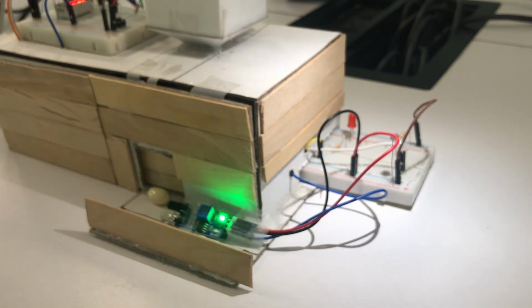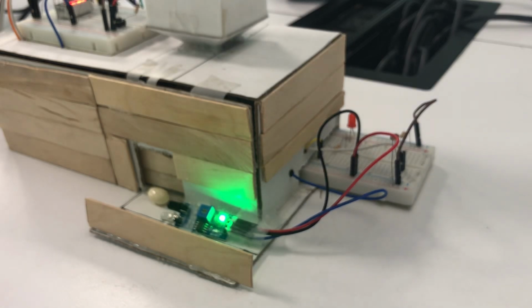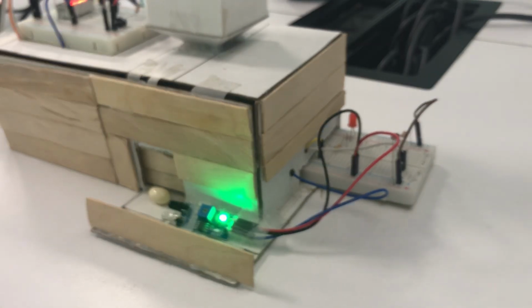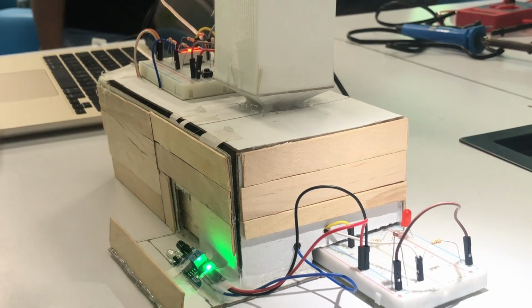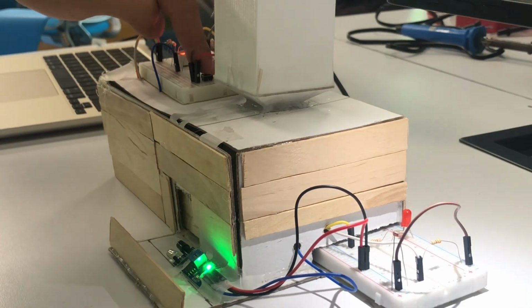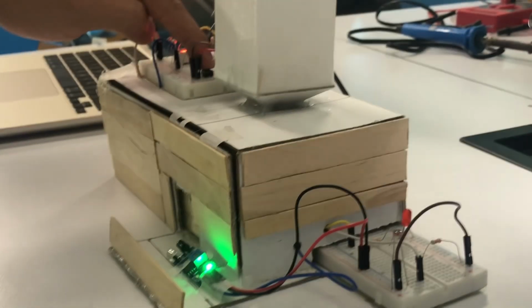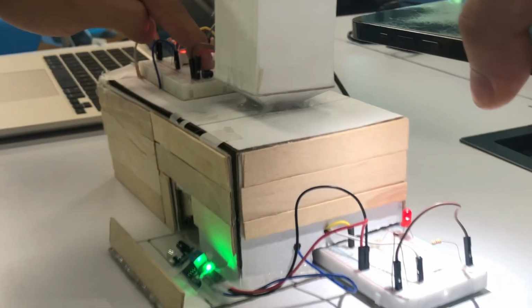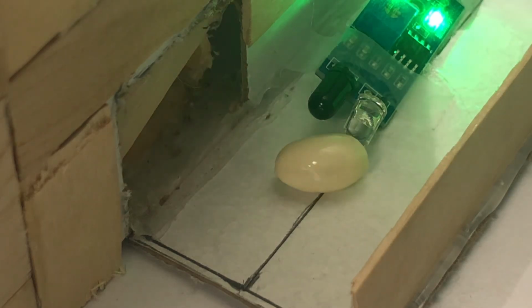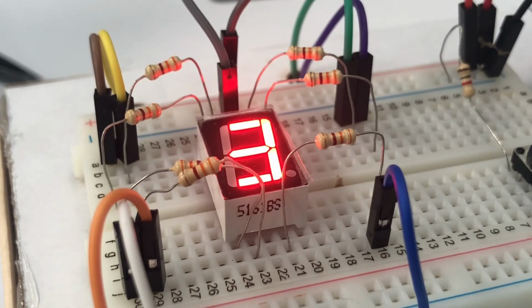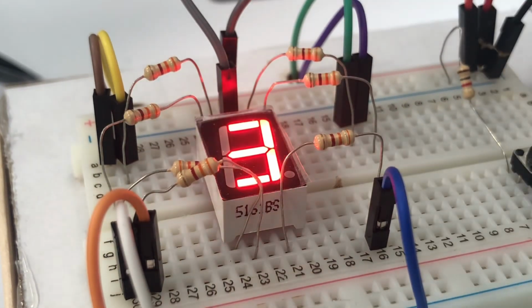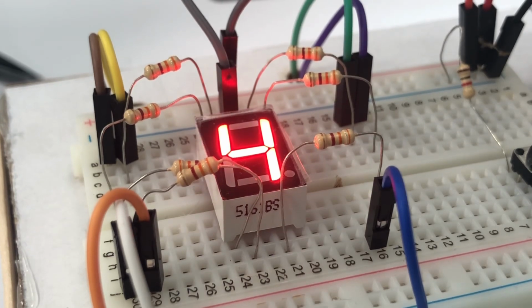The button only works if the LED is on, indicating that the amount of light is optimal, and will only work once per day. There will have to be a change of light for it to work again. Also, if the infrared sensor does not detect that a pill has passed it, it will continue to open the doors until it does. The 7-segment display is used to number the current day of the week. It goes from 1 to 7, and once it reaches 7, it will restart and the number of weeks that have passed will appear in the serial monitor.